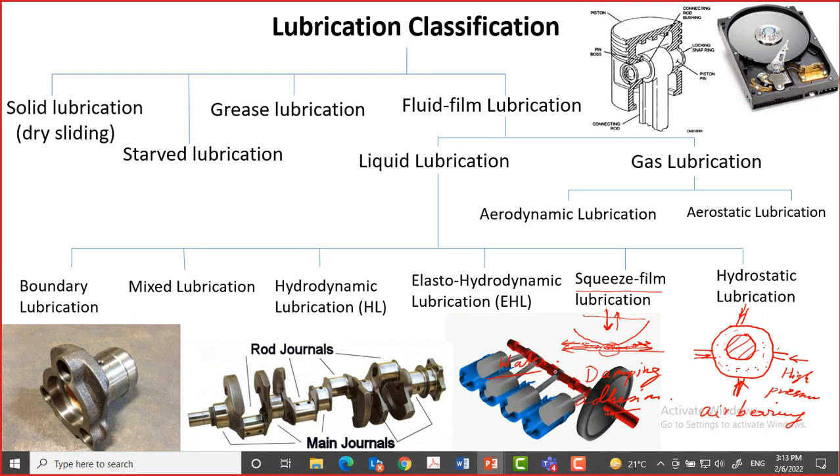And for the lubrication part, they actually experience all of these lubrication regimes at one point or the other. For example, from boundary lubrication to mixed to hydrodynamic to elasto-hydrodynamic. So all kinds of lubrication regimes, as they are called, exist in this case.